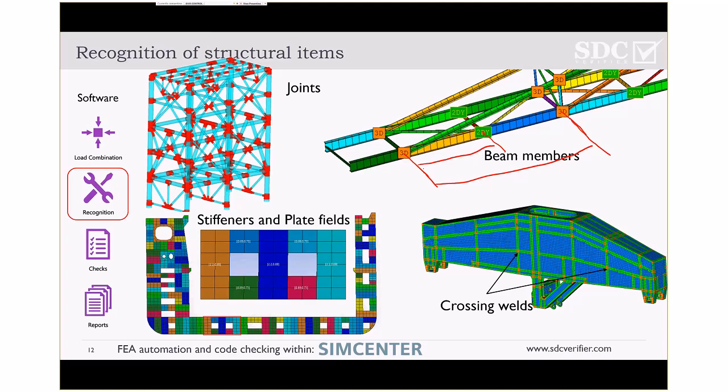And how do we do that? We recognize the connection, so this is what we call a 3D connection, while this is only a 2D connection. A 3D connection has a connection in all three directions, while a 2D connection has stiffness in only one plane. And that means that this 2D joint here does not split the buckling length over the principal axis in the vertical plane.